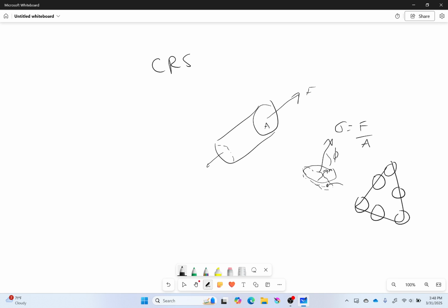That angle is usually given as phi. The second thing you realize is that, while that's the plane that's going to most easily deform, it's only going to deform along certain directions in that plane. So these are my closest packed directions right here. I'll just draw one, and I'm going to say that direction is lambda.